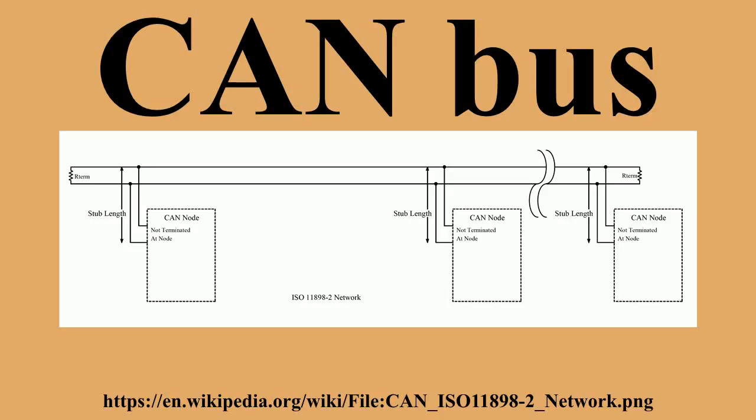During a recessive state, the signal lines and resistor remain in a high impedance state with respect to both rails. Voltages on both CAN+ and CAN- tend towards the voltage midway between the rails. A recessive state is only present on the bus when none of the transmitters on the bus is asserting a dominant state. During a dominant state, the signal lines and resistor move to a low impedance state with respect to the rails so that current flows through the resistor.